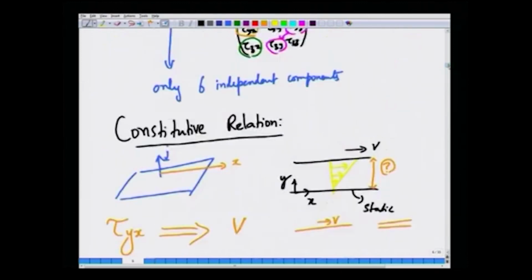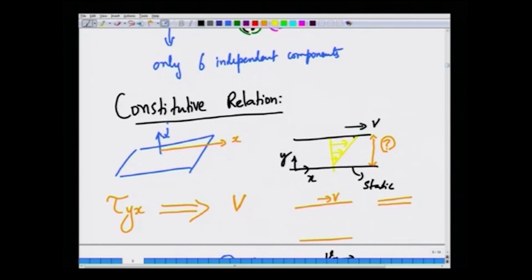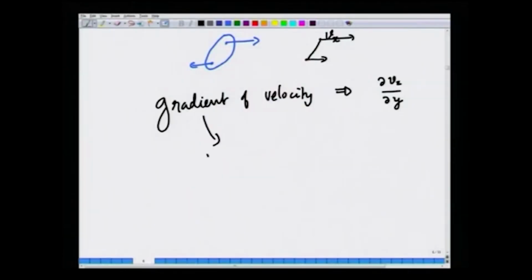In this particular case, there is indeed a variation in velocity in the y direction, so stresses will be generated. If both the plates are moving with a constant velocity v, then there will not be velocity gradients and no viscous stresses, because this amounts to merely moving the entire fluid as a rigid body. So, only gradients of velocity can generate stresses, not absolute velocities.